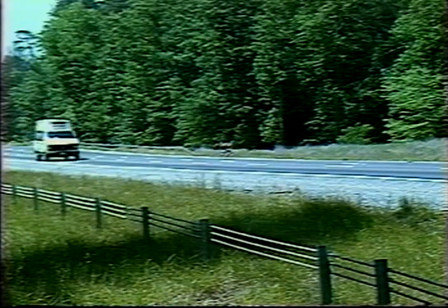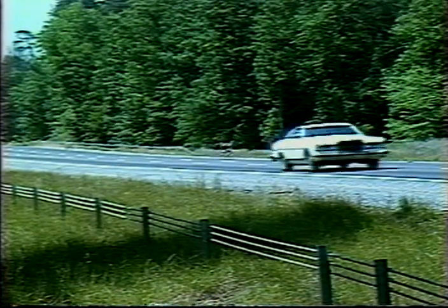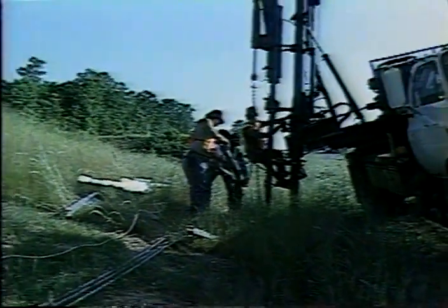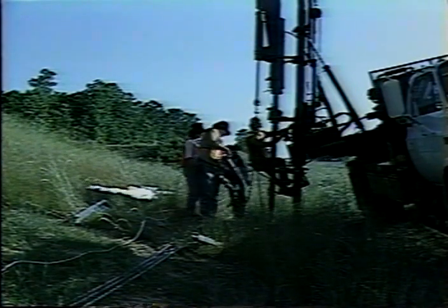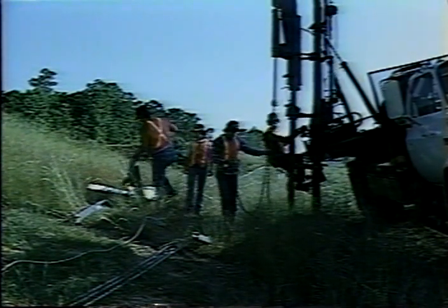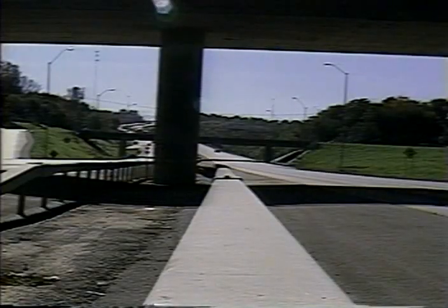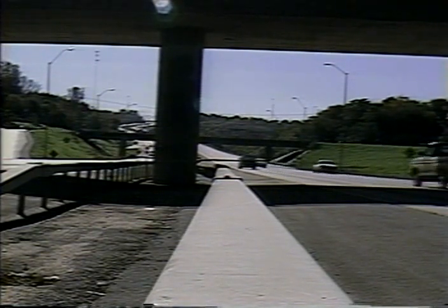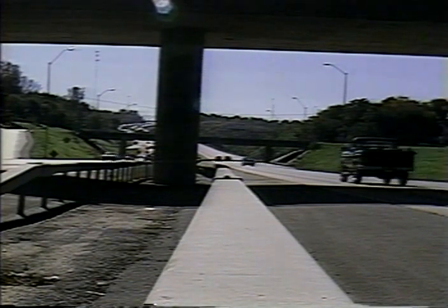In general, flexible systems that are more forgiving when they're hit are best for the driver. But unlike the more rigid systems, flexible barriers receive more permanent damage with each impact and cannot sustain repeated hits without immediate repair. The trade-off is to use flexible systems where they can be set away from the roadway and not be hit so often. Semi-flexible and rigid barriers, which are less susceptible to damage, can be placed closer to the roadway. This strategy balances safety and maintenance costs.